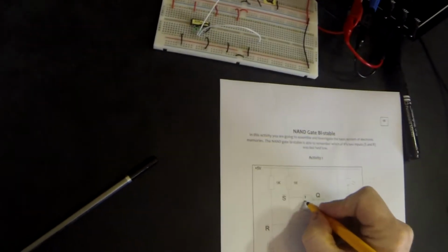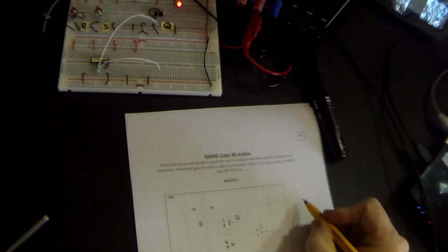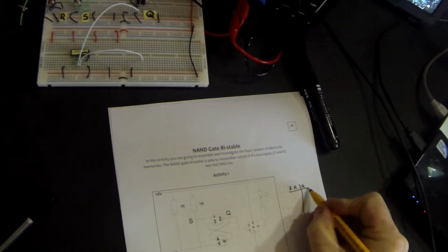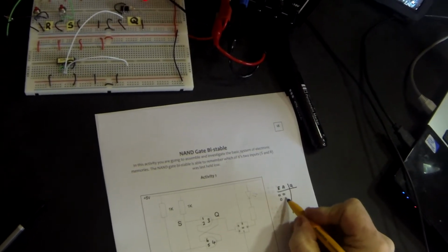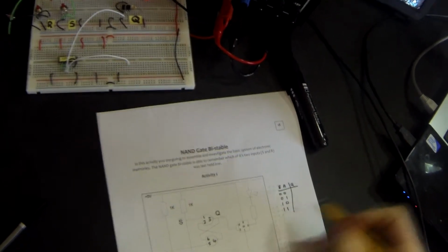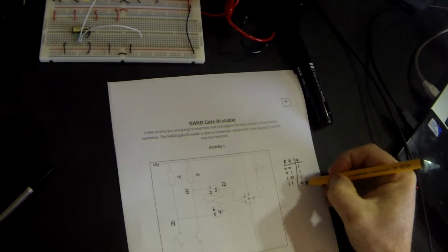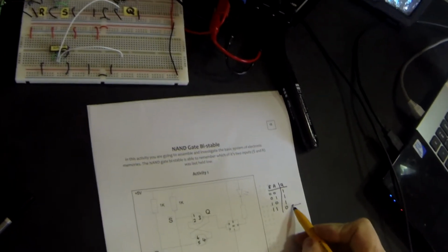Okay. So, having a quick look at our circuit, I'm going to number our pins, pins 1, 2 and 3, 6, 5 and 4. Let's remind ourselves very quickly as well about a NAND gate truth table. So the different possibilities in a 2-input logic gate are 00, 01, 10, 11, and the output of a NAND gate is this. In other words, this is the important one, because the only time we have a 0 at the output of a NAND gate is when both inputs are 1.